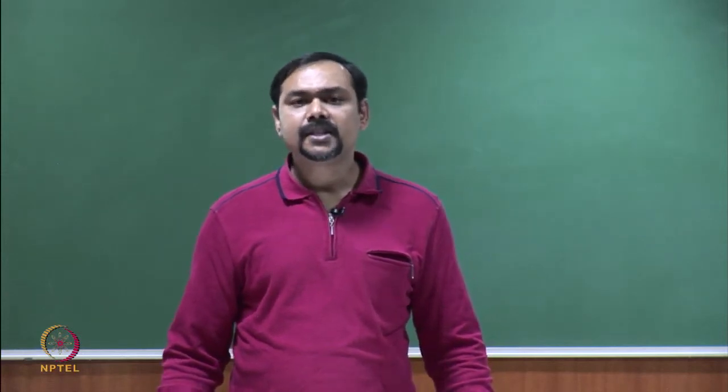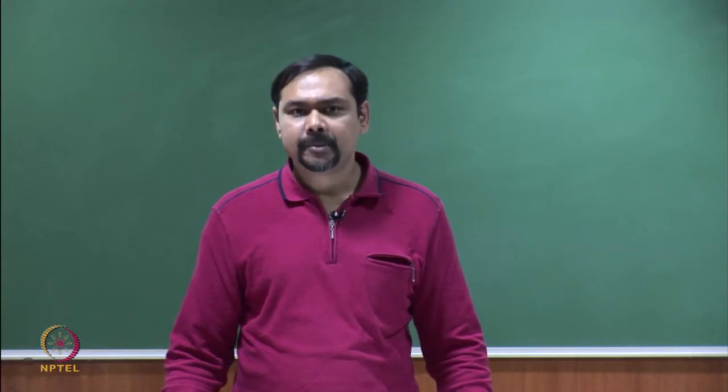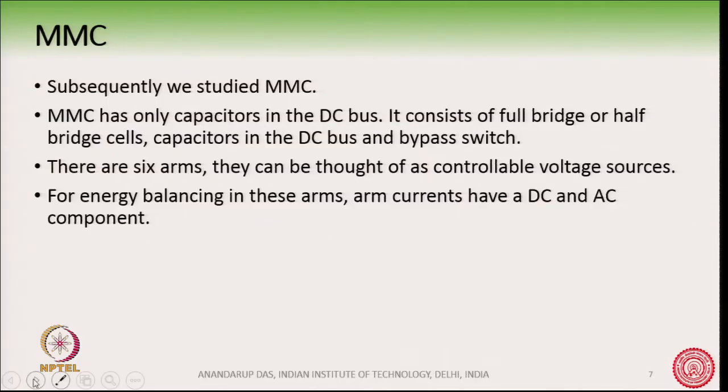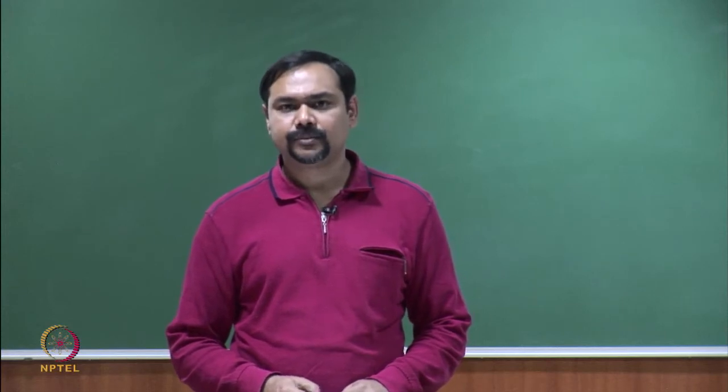So, from CHB we move into MMC. And why did we move into MMC? Because the CHB required isolated DC sources. That was the biggest disadvantage.